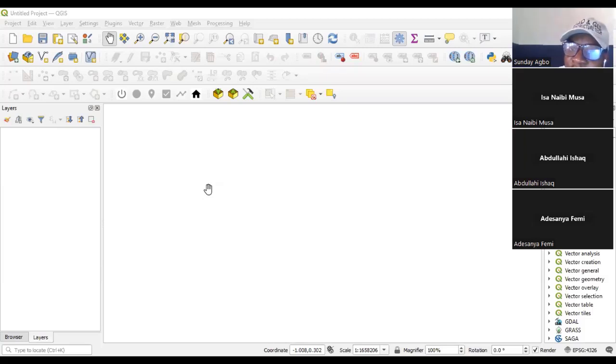But as I said, when it comes to issue of building management using GIS, the high level of accuracy is not required because we are dealing with locations, ability to actually see this is where my site is, and then this is where I'm positioning so thing in that site, and then this is where possibly I'll place my gravel, this is where we are positioning our store, this is where we'll be putting crane. You understand? All those kind of things, this is all we are considering as far as construction is concerned.